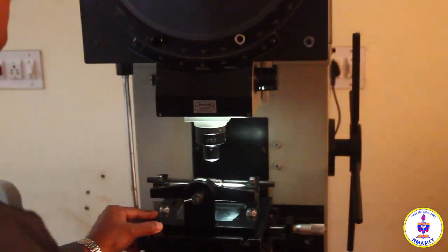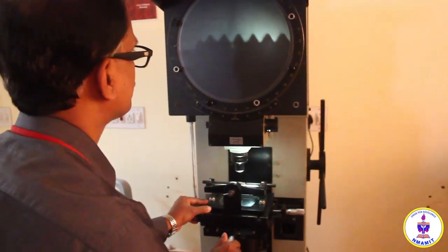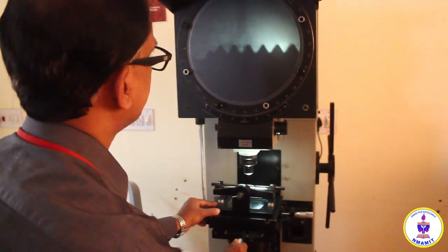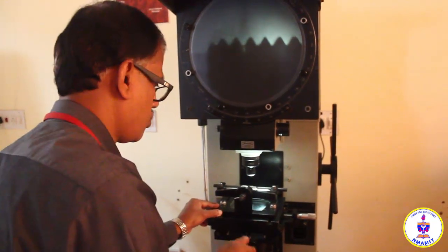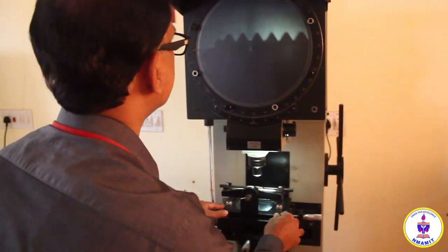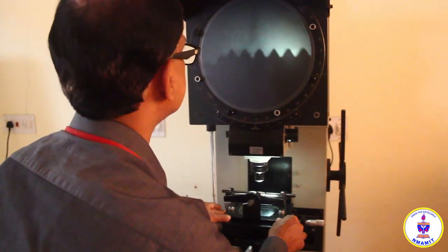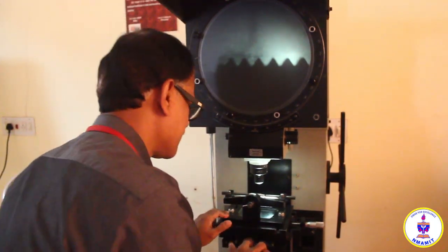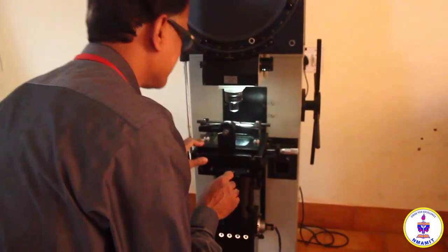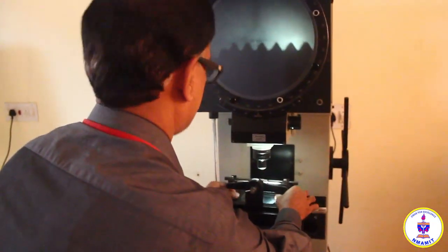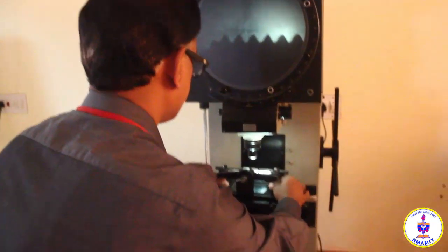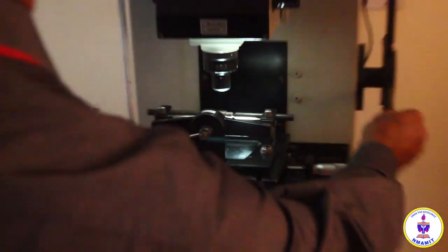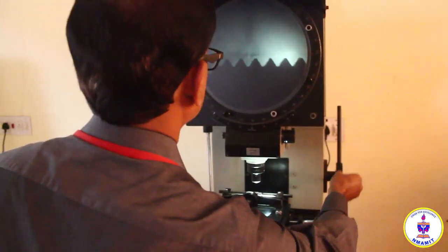Now while moving the micrometer here, see the movement of the image is like this. In order to measure, say, the major diameter, one reading is on this side and the next reading must be on the other side. For that I have to open this. For the initial reading, you place the shadow of the screw thread somewhere here. So it is now the beginning of the reading, and you can lock it now. Now I have positioned it for the measurement. Now the image is not very sharp. Make the image sharp by focusing it.